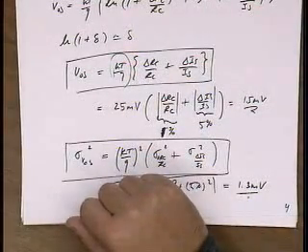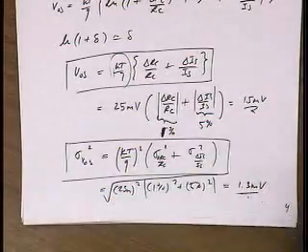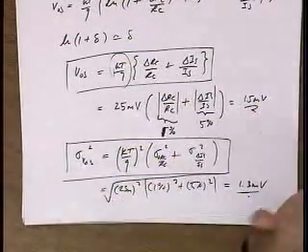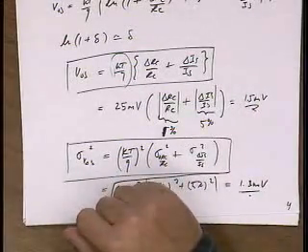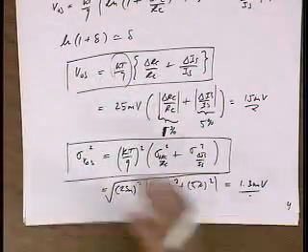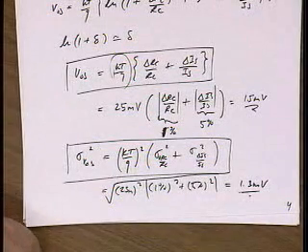And if you're in a really high precision application and you can afford it, you'd play with your material properties in such a way that their temperature coefficients cancel out and you can get a very low offset. But we don't really usually design circuits like that. We design circuits for mass production where you can't afford to trim parts individually.